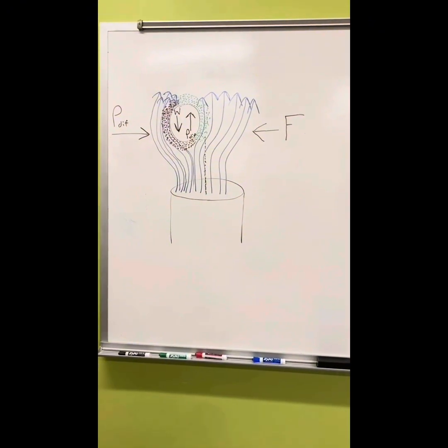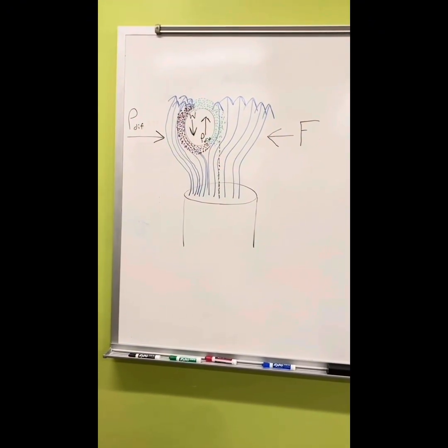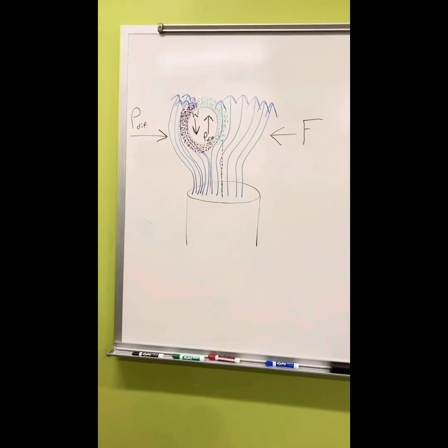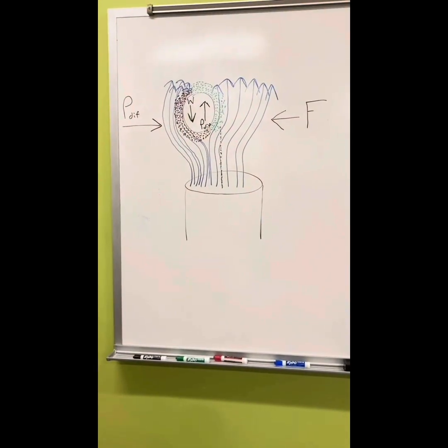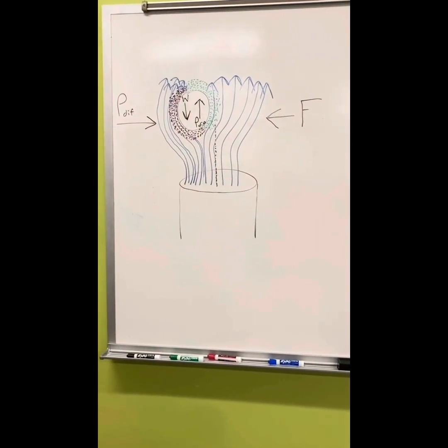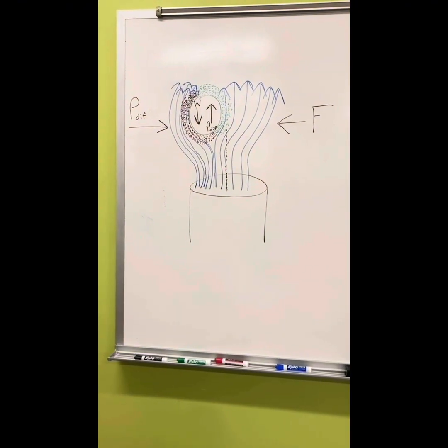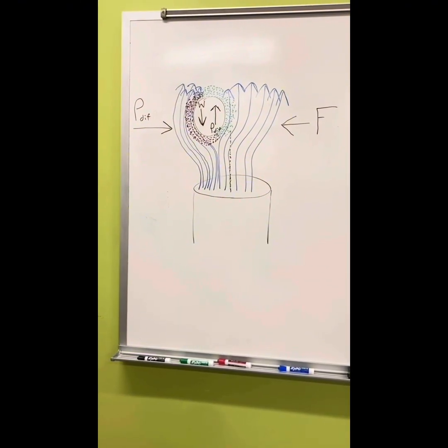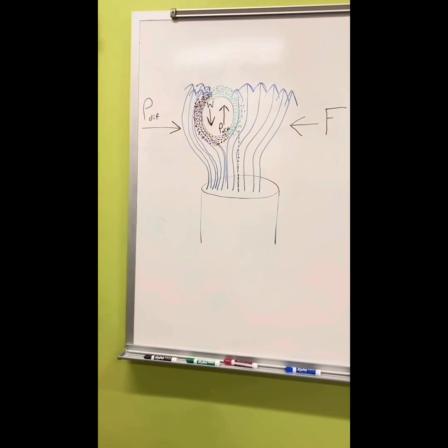If a horizontal force is applied to the ball, the airflow on the side that it's pushed into will have its velocity decrease, creating an area of high pressure. On the opposite side of the airstream, more area is freed up for the flow of the air, increasing the net velocity of the fluid on that side of the airstream, which creates an area of even lower pressure than before.